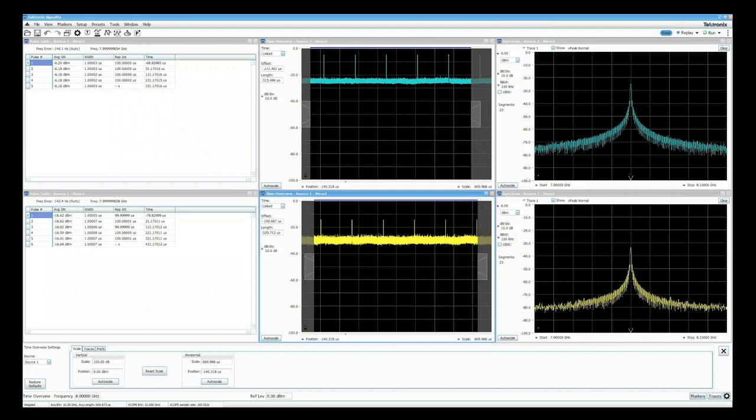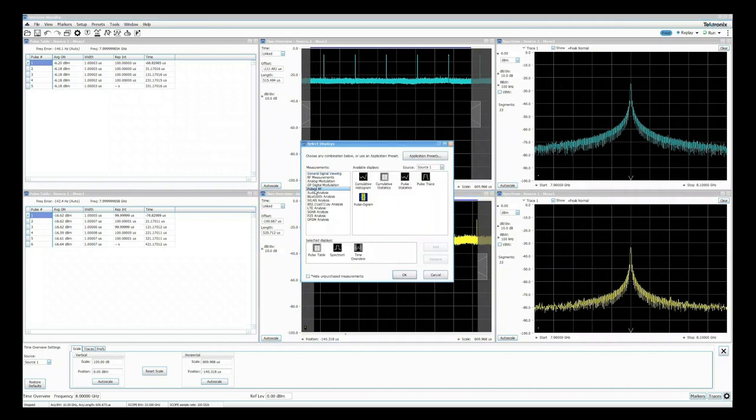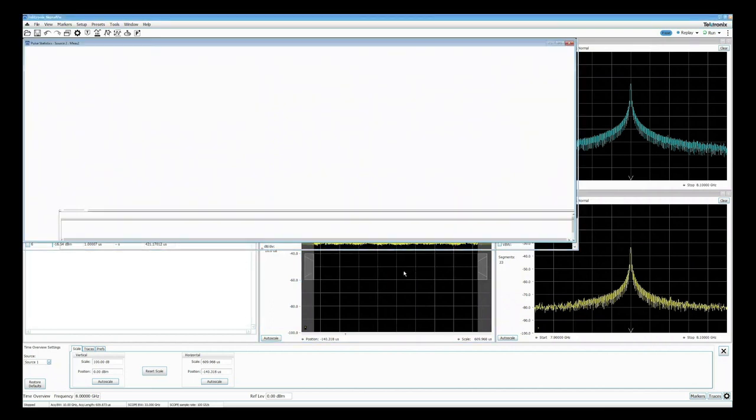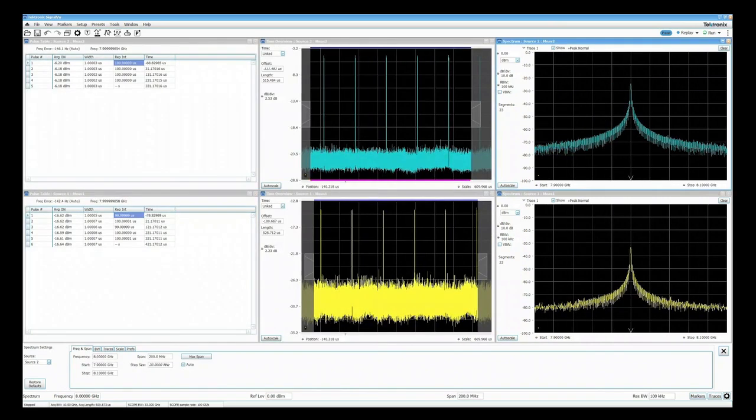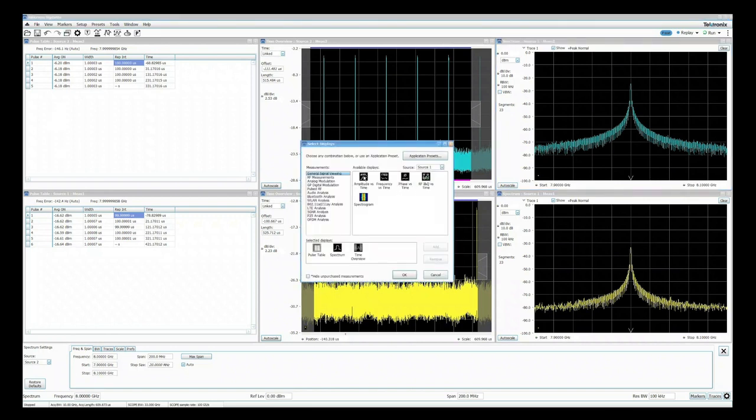You can also observe the time trend and measurement statistics using the pulse statistics display. With this display, you can see how the PRI varies across pulses over time. The pulse table provides information about the absolute delay between channels, or time slot, while the time trend reveals how this delay is maintained over time. Currently, we are acquiring only 5 to 10 pulses, but to gain a comprehensive understanding, we need to analyze over many pulses.